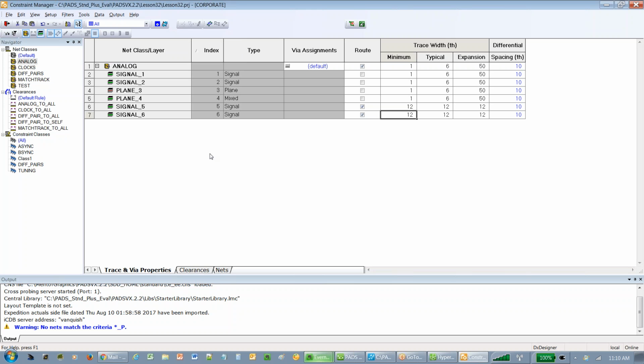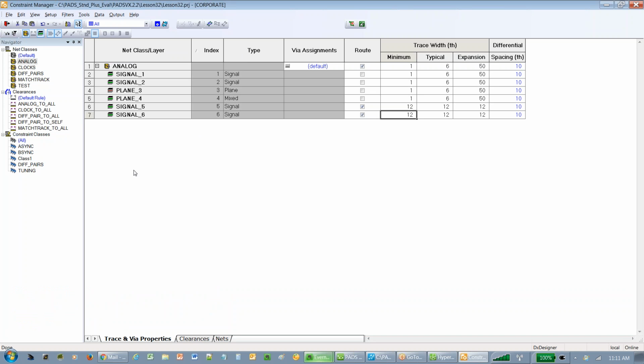I'm not sure where the button went for me here. It should have been right there, but as you know, PADS now supports three-dimensional placement capability. And in this tool, or in the constraint editor system, you can define all of your 3D constraints, so that you're not having to wait to get into the PCB space to do that. You can do things like component to component, component to assembly. It allows you to do real-time three-dimensional DRC verification in the layout application while you're placing parts.